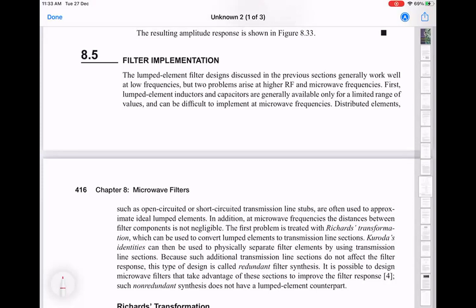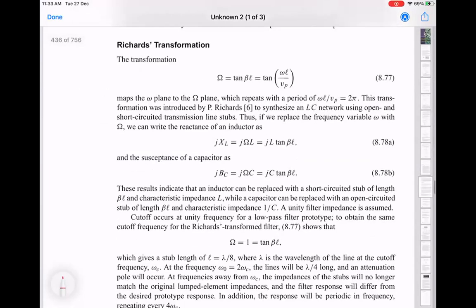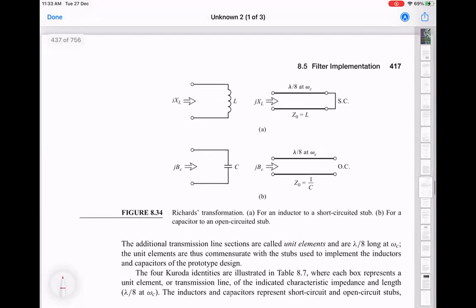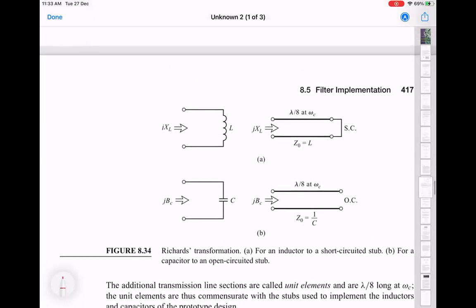Here, I'm not actually going to go through the detail, just going to show the basic idea, that there are some transformations which allow you to identify, and we have sort of done this earlier also when we looked at modeling how a resonator looks like a parallel LC circuit. We try to see how to get the equivalent thing. Similarly, just an inductor or a capacitor can be thought of as sections of transmission lines with different boundary conditions.